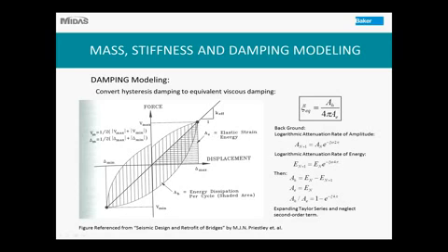In our classic structural dynamics governing equations, what we have is viscous damping. And hysteresis damping does not equal viscous damping. So we need to find the equivalent viscous damping, which is given by this equation here. And here is some background of where this equation comes from. Basically, it's just a first order approximation of a Taylor series expansion. By the way, this is a conservative assumption here, and